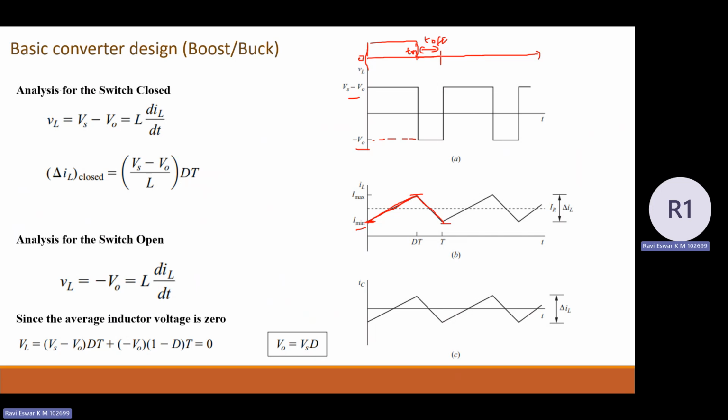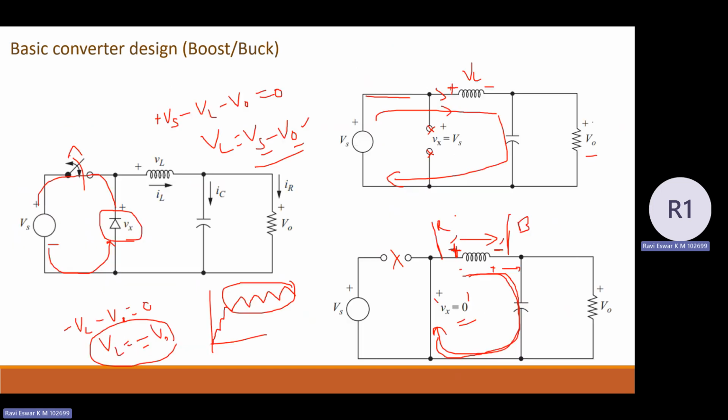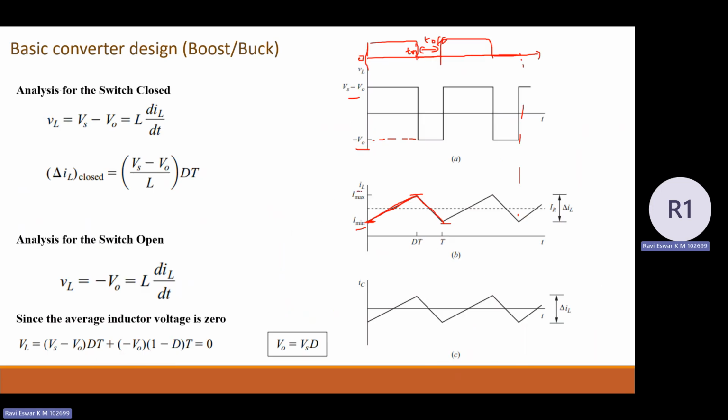Again when I turn on the switch, the inductor starts charging with a gate pulse applied to the switch gate. Again, when I turn off the switch, the inductor is in discharging state. So this continuously repeats. Now you can check here the graph of inductor current and inductor voltage.